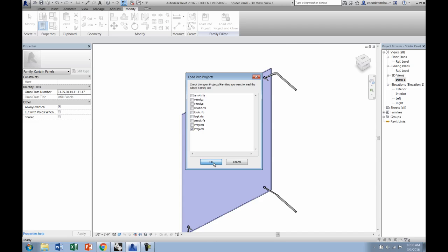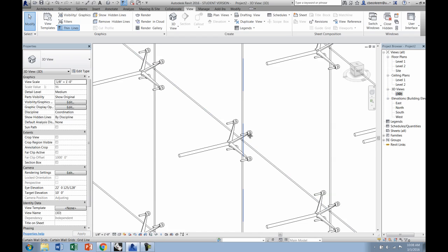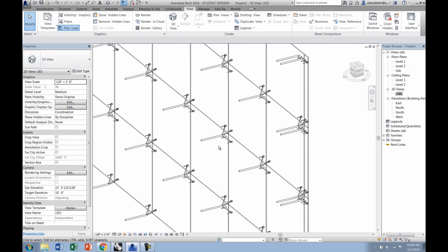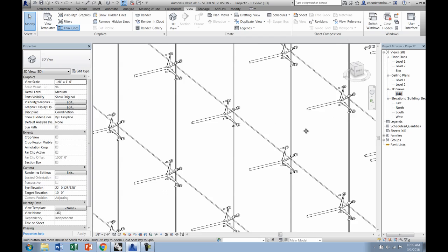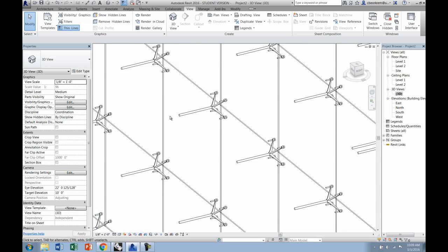So each time you add a piece to this, overwrite the existing version, pop into 3D and take a look at how it looks. So again, we've got a funny spot here on the corner if we change the dimension, but this is looking correct. So you'll put the little clippy that'll hold the truss component right here at the base, and at the top of this rod as it's going, you're going to want to snap it to those two reference planes.